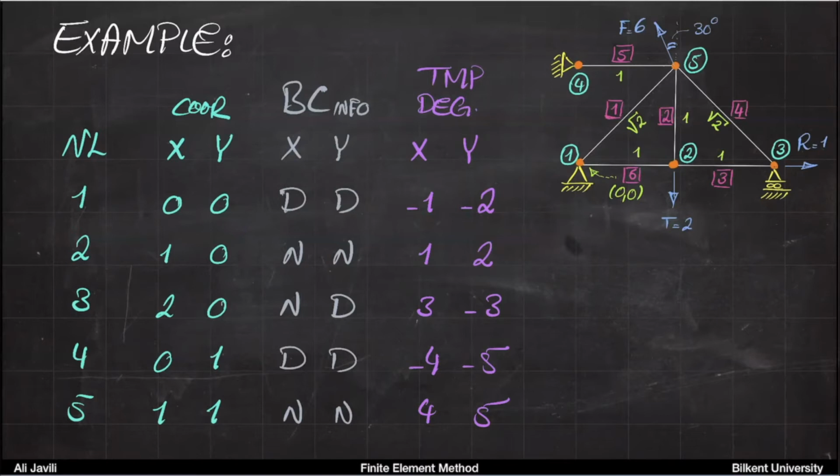So this process is exactly identical to what we did. So what is the largest positive number we see here? 5. So degrees of freedom, then it's 5. We have 5 degrees of freedom, which you can actually see from the picture. So you have 2 degrees here, 2 degrees here, and 1 degree here. So you have 5 degrees that are free, they can move.